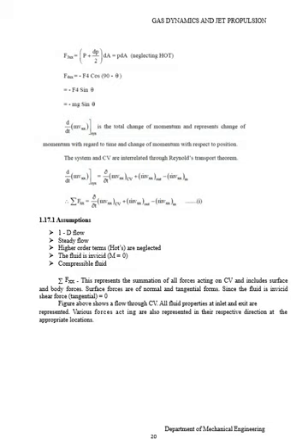Assumptions. What are the assumptions for this flow? One-dimensional flow, steady flow, higher order terms are neglected. The fluid is inviscid, that is viscosity is equal to 0. Compressible fluid. Therefore, summation of Fx represents the summation of all forces acting on a certain volume, the control volume CV, and includes surface and body forces. Surface forces are of normal and tangential forms. Since the fluid is inviscid, shear force is equal to 0.